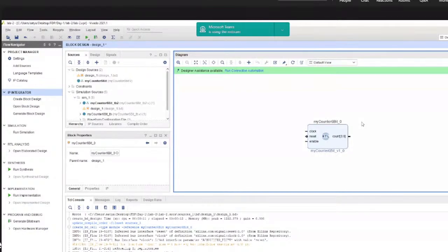If you have an existing IP, in industry standard, what people will do is, to the maximum extent, use the IP cores. Why? Because these IP cores are already designed and fully tested. So people will not waste their time designing the basic building blocks. If they want a counter, they won't redesign the counter by writing Verilog HDL code. Instead, if an existing IP is available that is fully tested and authenticated, they will take that IP, put it into their design, and reuse it.